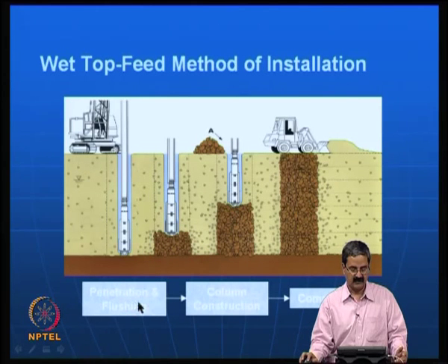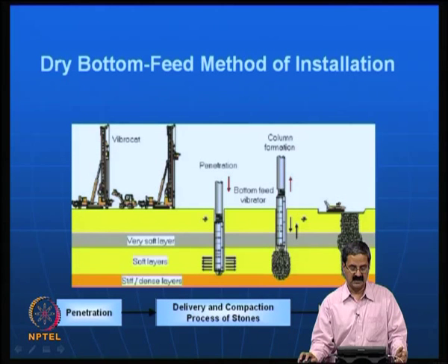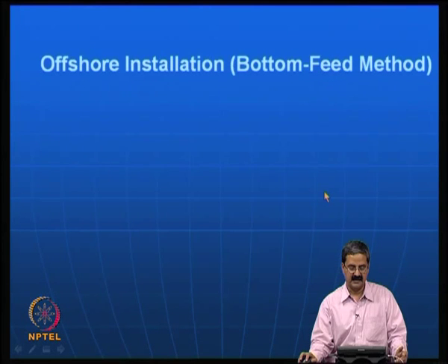You have penetration, flushing, column construction and completion. So, this is a dry bottom feed method of installation, where you try to do in this manner. You have a penetration, delivery and compaction process of stones, completion. So, these are some differences that we have, based on installation techniques.